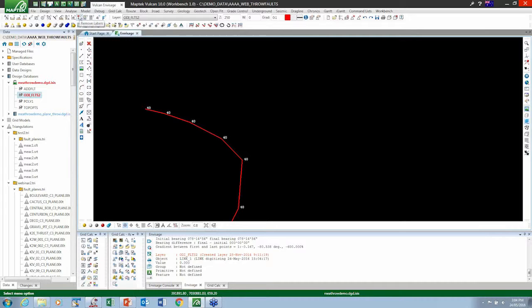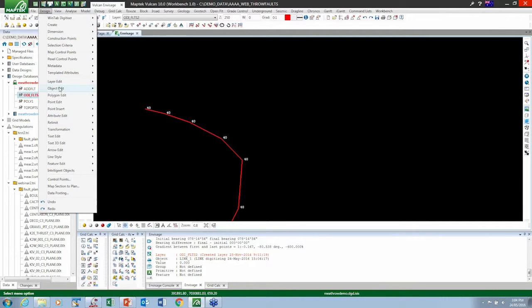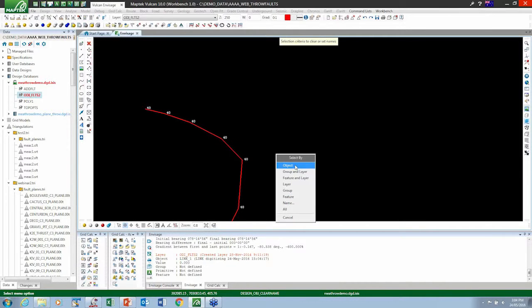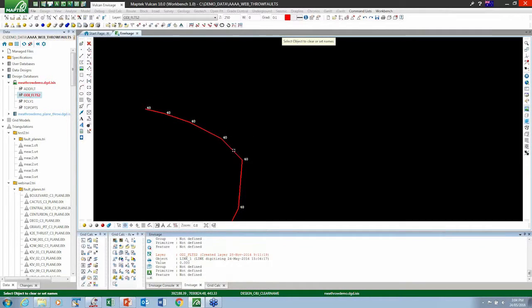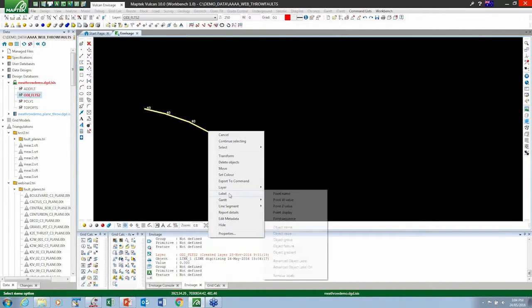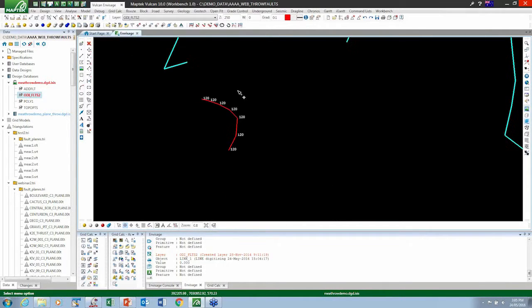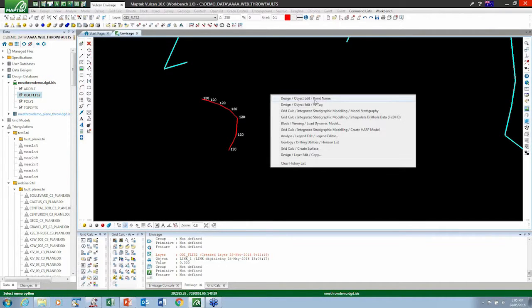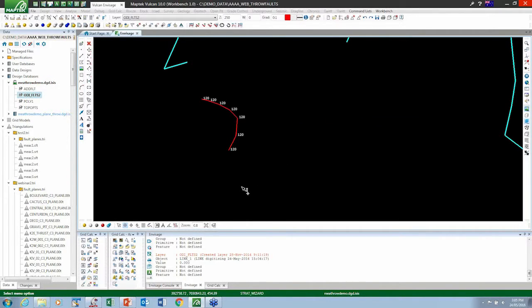Well, I think it's a reverse fault, so I'm going to change this and make the actual point name, I'm going to give it a dip of 120. Okay, and I can check that quickly by labeling that. There's my dips. So now if I save that into my layer, I can simply rerun using that new information.